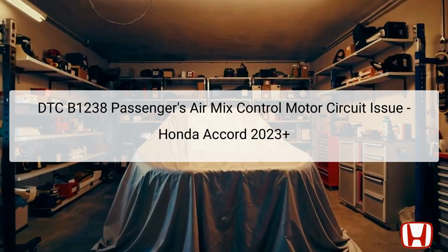The diagnostic trouble code, DTC B1238, also known as DTC indicator 45, indicates a problem in the passenger's air mix control motor circuit within the Honda Accord 2023 and newer models. This issue relates to the vehicle's climate control system. Specifically, it may involve the air mix control motor, linkage, or door.